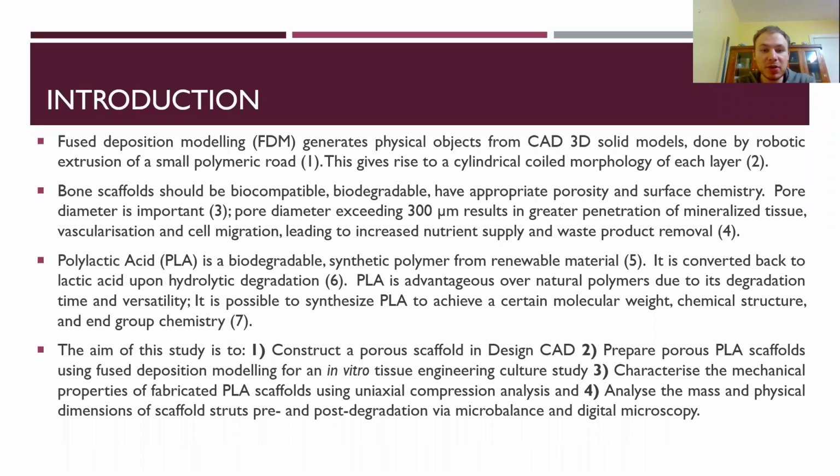An alternative is to engineer an osteogenic scaffold. For scaffold design, the aim is to produce a scaffold that can modulate the process of healing while simultaneously providing mechanical support without igniting a stress shielding response from the body. The material should ideally degrade in parallel with the production of new bone matrix.